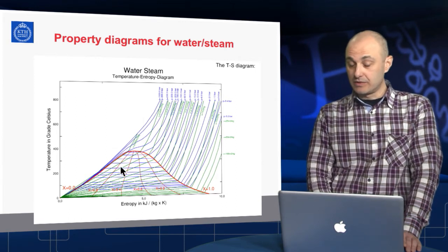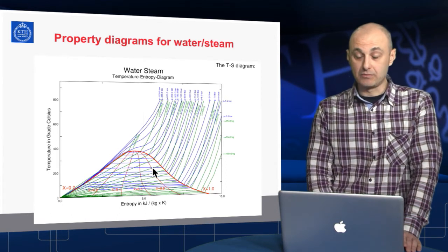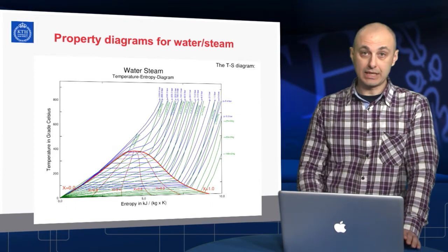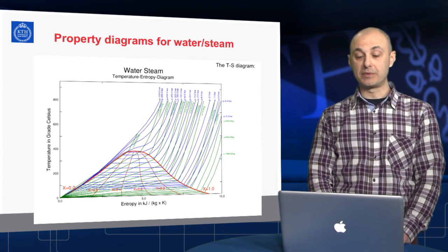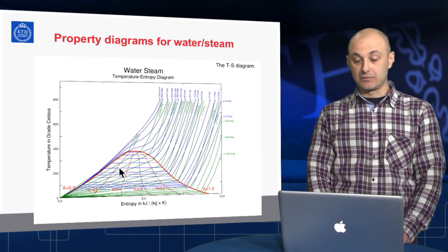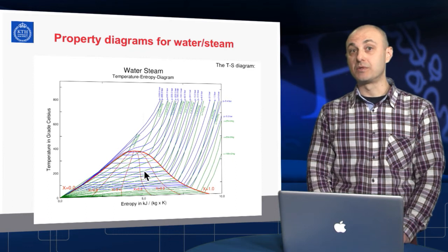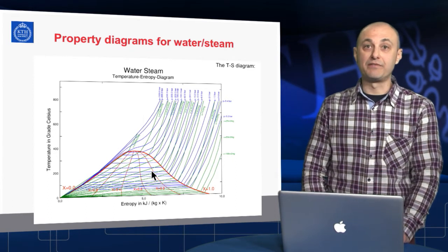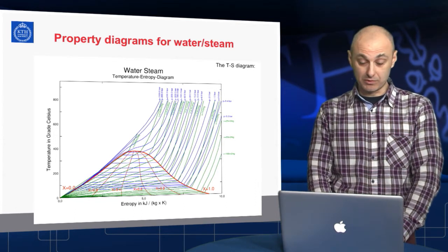Temperature being constant and running along the same pressure line within the double phase zone. Please don't forget that. When water or any other single simple substance is boiling or condensing, temperature and pressure are linked to each other. The easiest way to remember it: 100 degrees Celsius, 1 atmosphere, water is boiling. That's how Anders Celsius in Uppsala 300 years ago defined the centigrade degrees and gave his name to those.